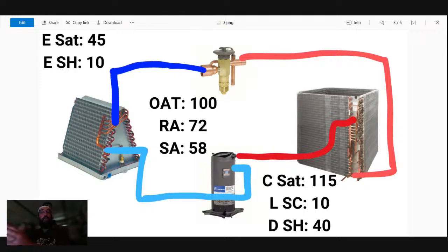If you're still not quite happy with it, or if you want me to return anyway, then we can come back. I can take some more humidity readings, and if we're still seeing after that time frame that they're running higher than 60% humidity, and we still don't see quite what we're looking for, then I would suggest dropping that down to that low speed.